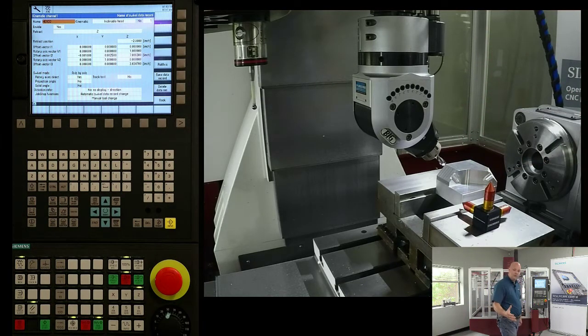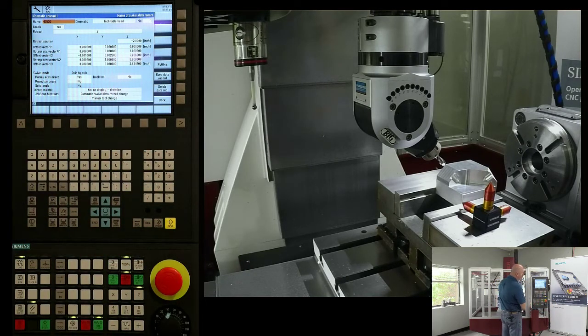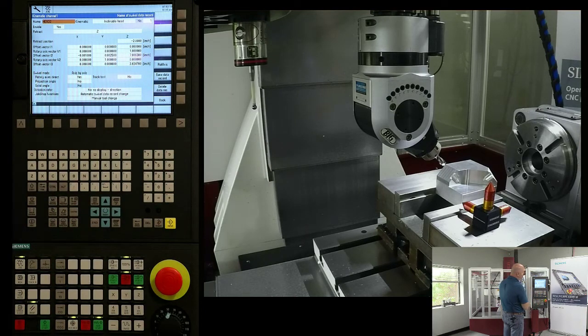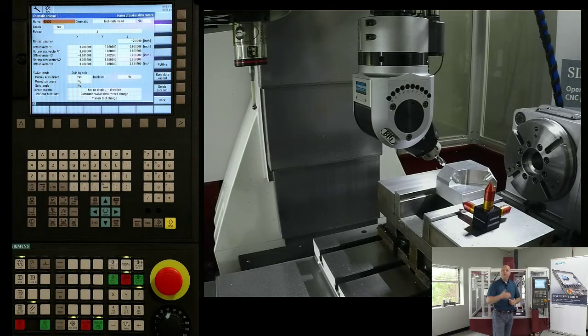And those values are what gets plugged into this table you're looking at here. So for those of us that get on a machine that has the swivel cycle enabled, whether it's full 5-axis or a 3-axis with a couple manual rotaries like we're doing today with the Big Kaiser adjustable head, you can see those lengths are plugged into different vector components within what we call the kinematic chain, or the chain that establishes where the tool tip is.